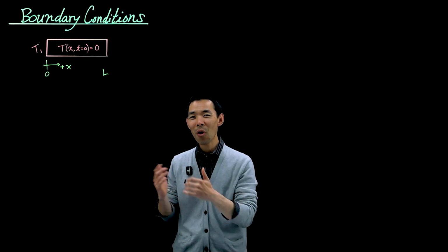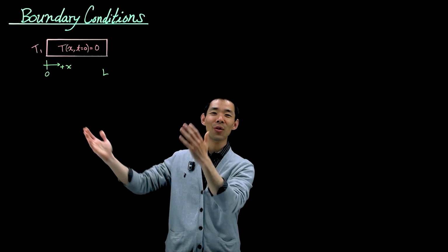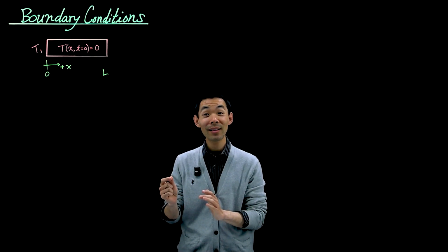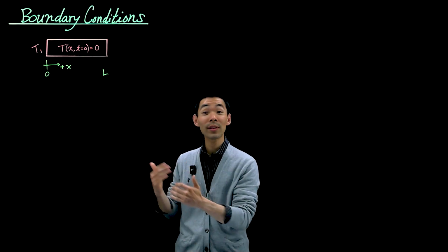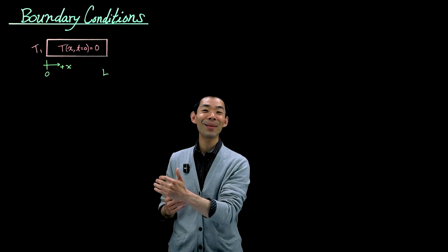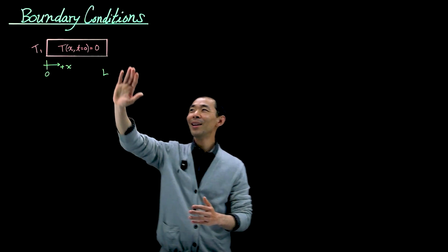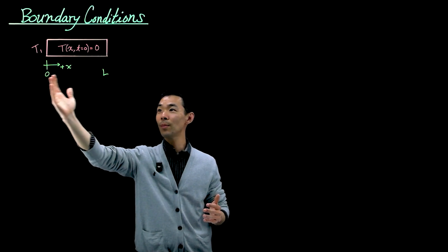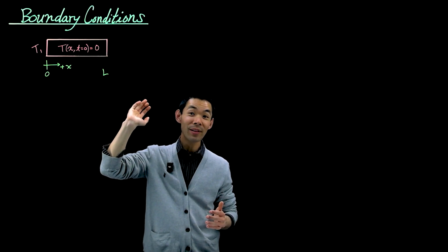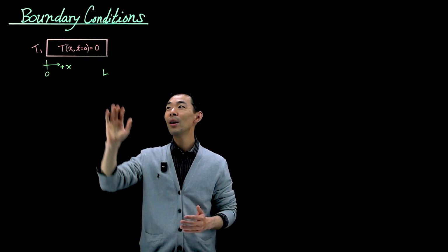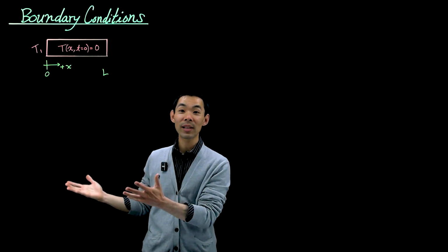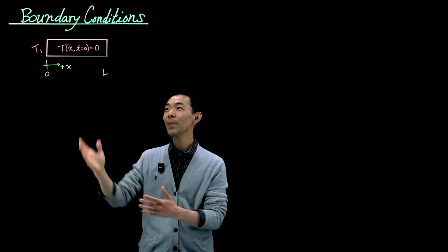Now, just to get warmed up to the broader question of boundary conditions, let's consider a small variant of the problem that we've been working on. We're just going to slowly build on it. So we have a slab. It's a one-dimensional problem as a function of x going from 0 to L. We'd like to solve for the temperature profile inside the slab when the left-hand boundary is fixed in a hot reservoir at some temperature T1.